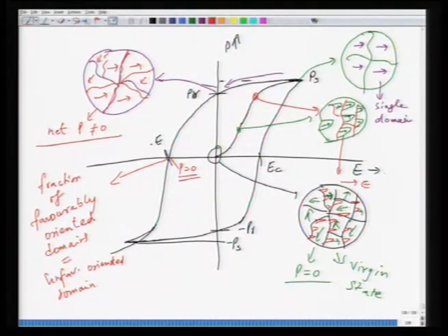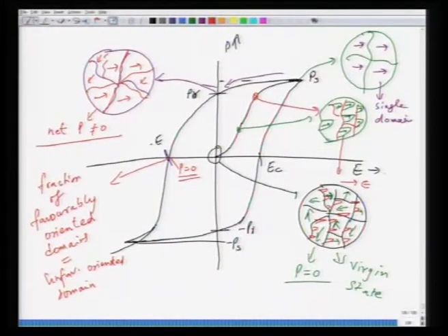Not only is a ferroelectric material, as we discussed earlier, a non-centrosymmetric material with a unique polar axis, but the unique polar axis can also be reversed. So, you have a plus PR state and a minus PR state, and this is what makes a ferroelectric extremely useful from the fundamental and from the application point of view. I will show you one animation for this domain wall reversal, how it takes place in the materials. If you just bear with me for a couple of moments, let me just find it.